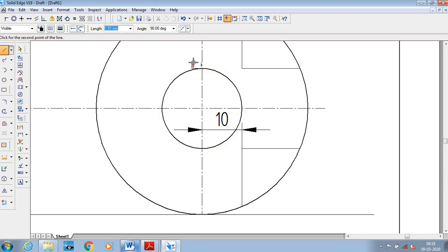Then the height is the thickness, you know what is the thickness, right? That is d by 6, therefore 3.33, and again 5 and 3.33. Is it correct? No, this is wrong, because as I said in the previous view, this keyway should be in between that of the shaft as well as the coupling, so therefore it should come in between.